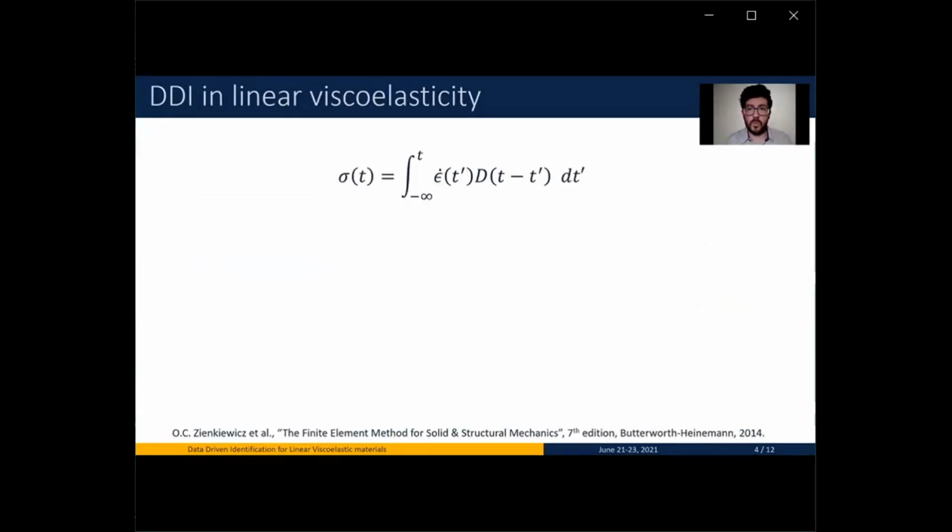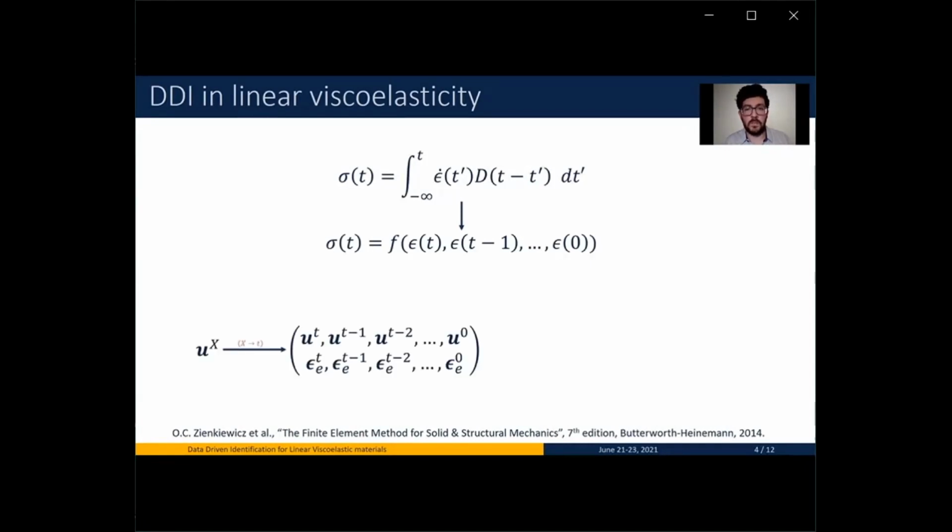So this previous approach was conceived for elastic materials, where each stress is unique to a strain. However, in the case of linear viscoelastic materials, stress is also dependent on the past strains. So to account for the history of strains, we extend the phase space. Each of our previous X deformed states are now steps in time, and the minimization problem includes the history by including all these steps in the energy norm, so we effectively increase the dimensionality of the problem. As a result, we obtain again an estimation of the stresses in each step, as well as the database of points independent of time that samples the problem.